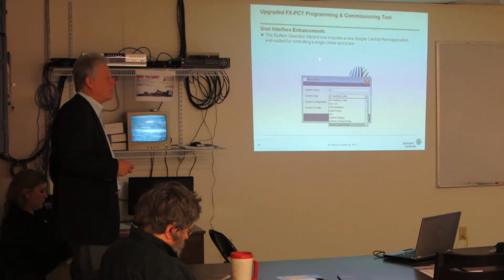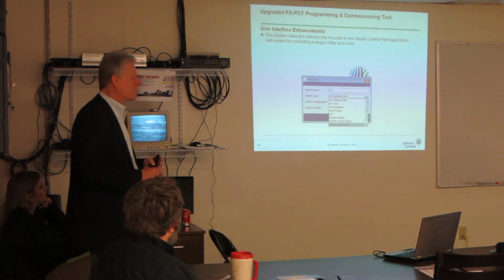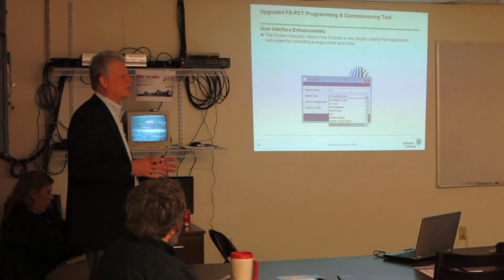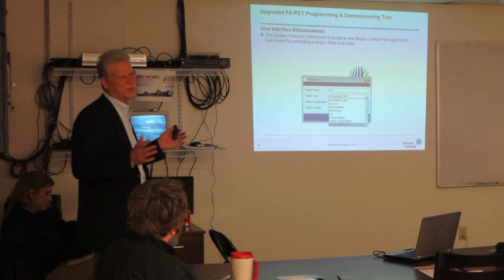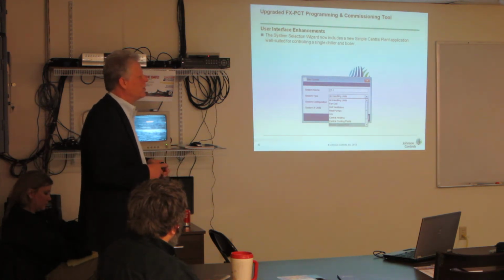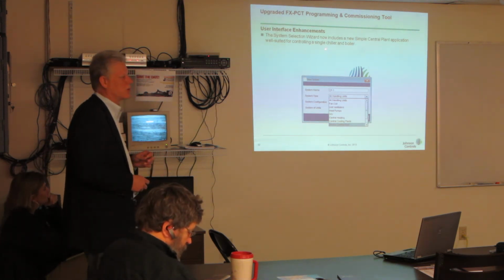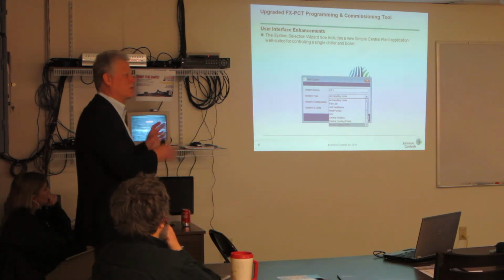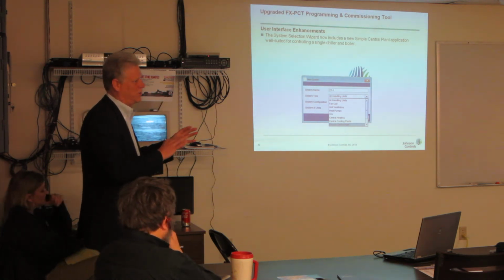You can actually now, if anybody remembers our old HVAC Pro days and then the new days, where you pick an air handler routine and you download into the controller. Well, say if you had an air handler and maybe you wanted to do a VAV box in the same controller, you were never ever able to do that. Well, now, at least we did get a start on it, you can actually do a boiler and a chiller program in one controller. So you don't need a separate controller for a chiller and a separate one for a boiler. One controller, and you can put their 2 different sequences in one controller. It's pretty slick.